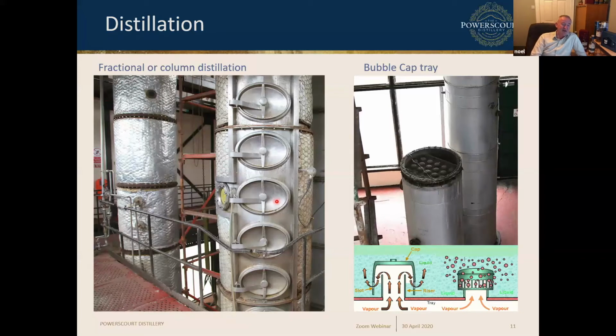So the wash is going in at the top, going down through the column and out the bottom as spent wash. And you can see that sight glass is a yellow liquid, so you can see that it's corn. If it was wheat, it'd be much browner, but that's a corn wash going through there. So once you have your spirit coming off there, it comes off around 45% alcohol that's collected, and then it's fed into the column on the left. Now, in some cases, you can have an intermediate column, and we'll talk about that in a few minutes. But we're just looking at a rectifier here at the moment.